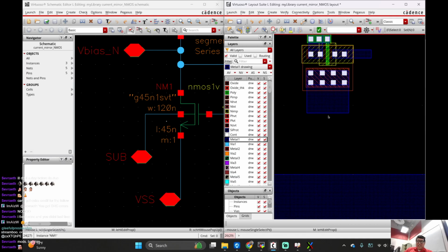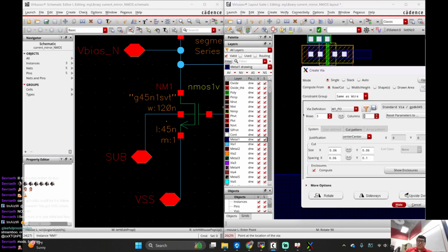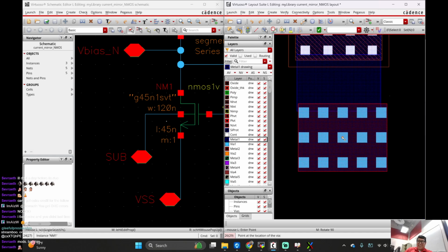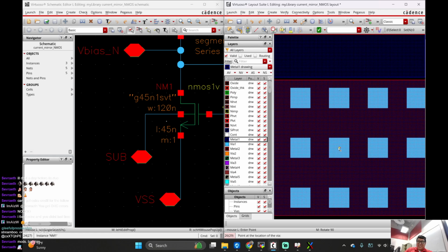Anyways, I'm gonna use a via to go to metal 2. M1 to metal 2 to metal 1. That's my favorite number, 3 by 3. Let's do 5, 3 by 5. Is that wide enough? I think I like that. Do you like that? What do you think?